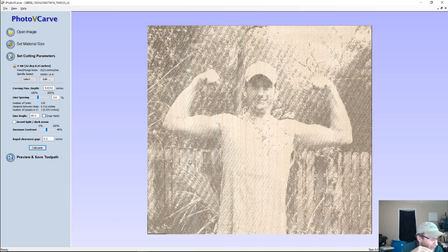Or I use a flat bottom V-bit as a rounding tool for square stock to round on my 4th axis. Now I've used my 1-inch surfacing bit, but I used to use a flat bottom V-bit because the angle of the V cutter was real nice for not being so aggressive on the corners and things like that.